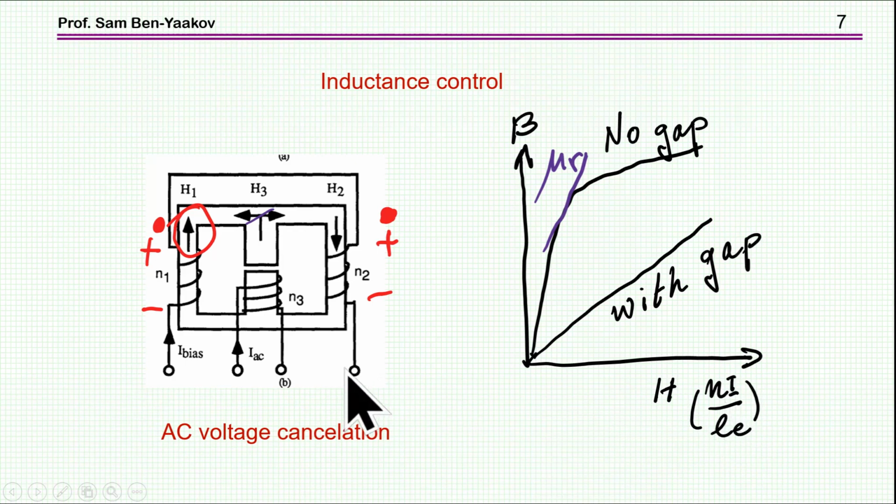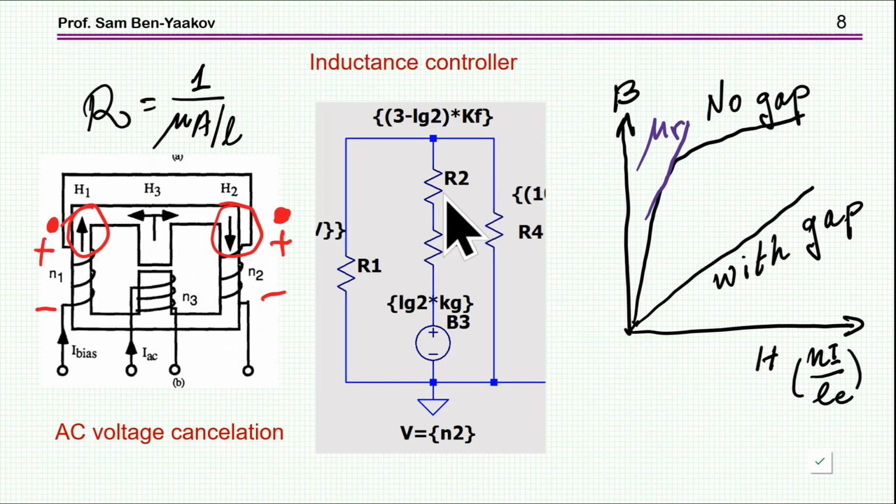So this is the idea here, that on one hand, the inductor is built around a gapped ferrite, while the DC sees only the ferrite path without any gap. Now you can describe this structure, which you might call integrated magnetics, by this reluctance model. If you are unfamiliar with magnetic circuits, there is a video on my YouTube channel which describes magnetic circuits, reluctances, etc., with an example, and I highly recommend that you watch it.